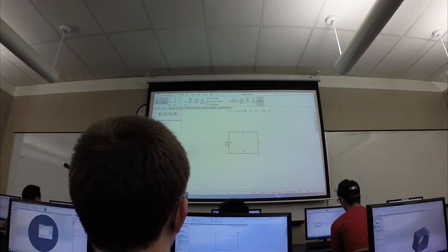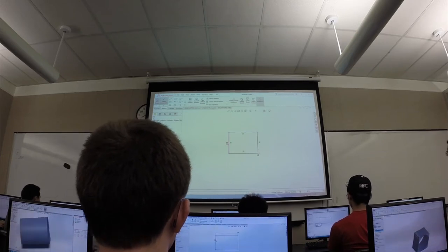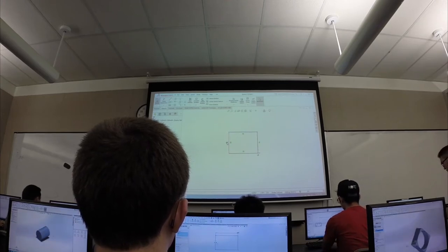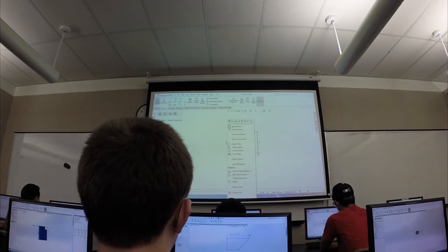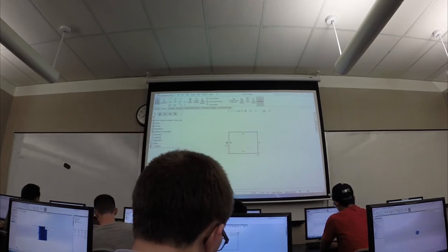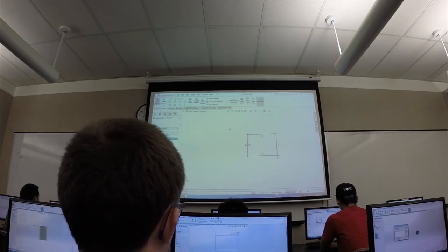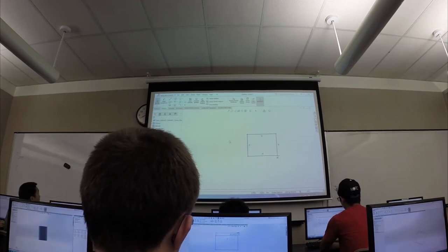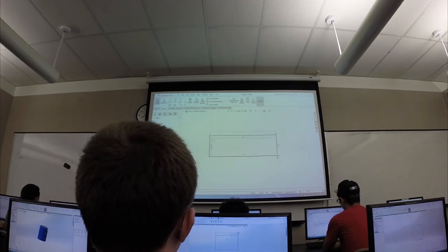We're going to cancel that for now. Let's get rid of that fixed geometry. You can click on it and then press delete. There we go. When you select that relation and then press delete, the relation disappears. So now our box is freed up again to be sized.